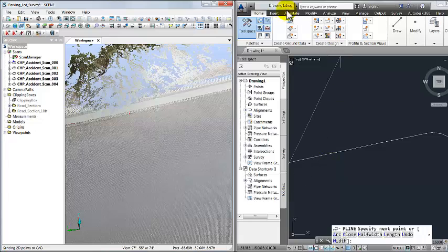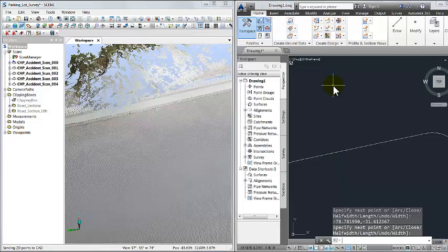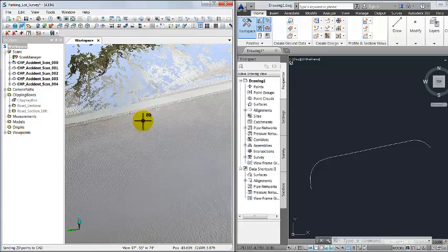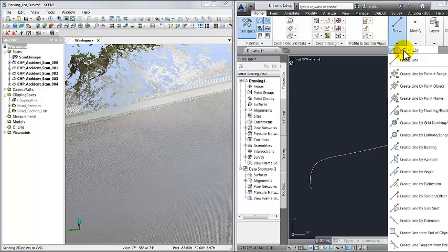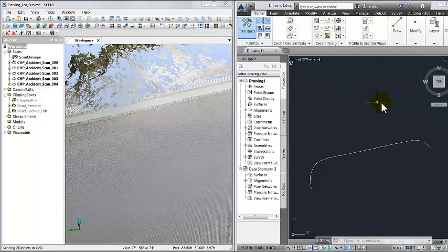We're going to go ahead, go back to AutoCAD and hit enter to finish that function up, and you can start to see some of the line work that you've drawn in there. So that's sort of the line work function. Same deal if you want to create lines, arcs, whatever the feature is you want to draw in CAD. Get to the point where you're ready to draw that feature and go over and pick whether you want 3D or 2D coordinates selected, and the Scene software will then allow you to go ahead and transfer those over. So that's the line work portion of it.